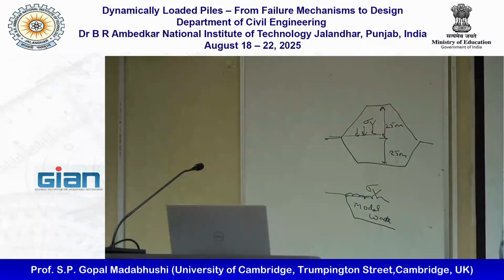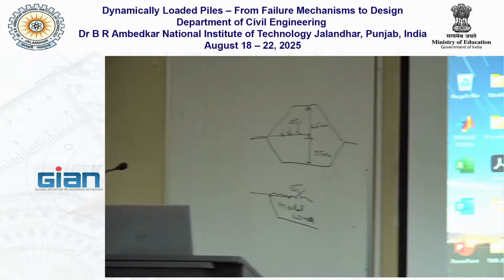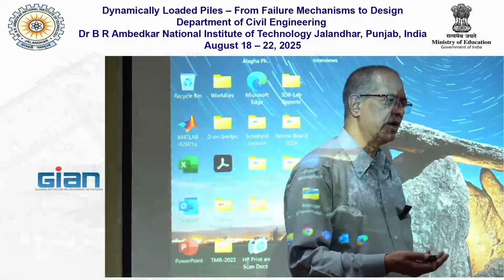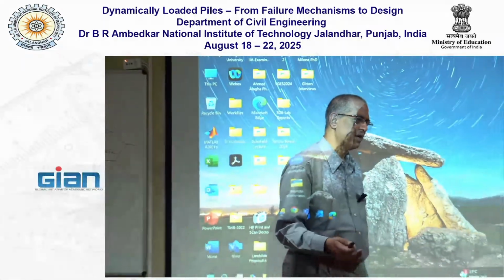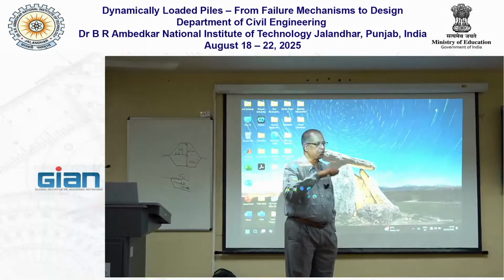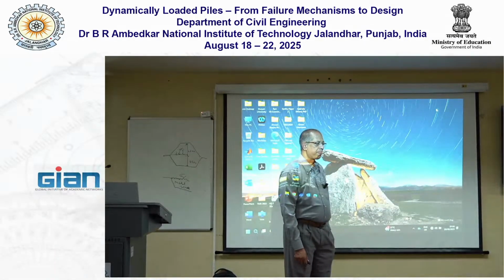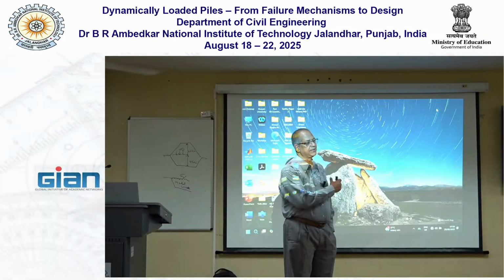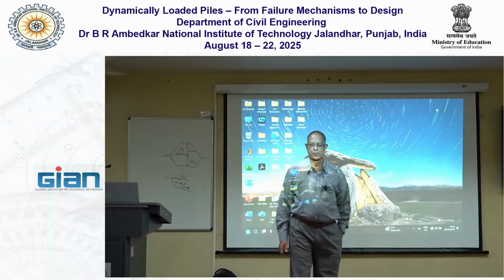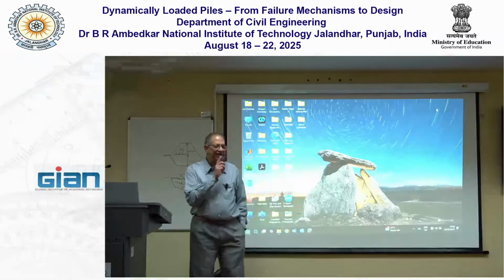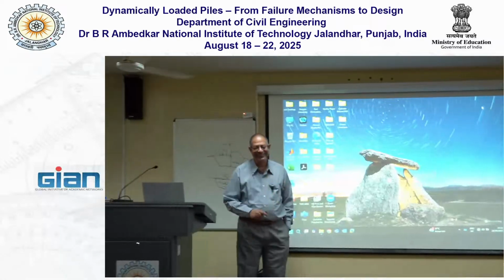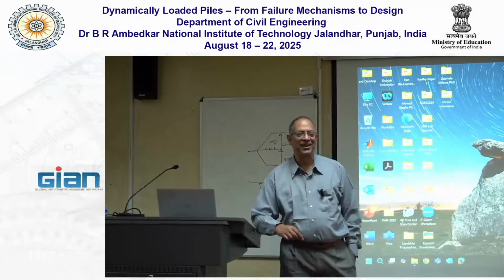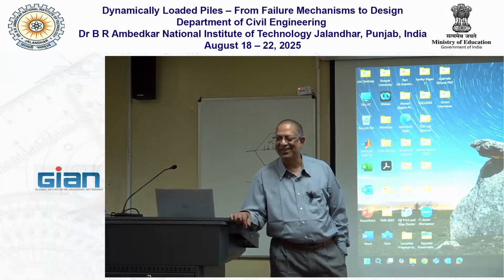So this surcharge is applied before the earthquake. It's there before the start of the centrifuge. So you get some settlement under the application of surcharge. Those are all monitored, so we know how much it would settle back. So you can rework the density of the waste. Normally, we don't make silly mistakes like that. Occasionally you may catch me, but the student is very good, so he wouldn't make stuff like that.